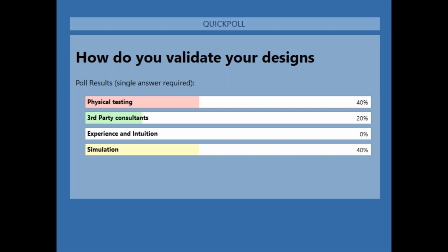So what we do, I'm not saying no physical testing at all, because we test our systems all the time. But these tests are generic, and then maybe run a simulation and compare at least your deflection, your displacement in the simulation software to what you've actually got on the probes during the physical test. That's how, through experience and being involved in testing, I validate my own simulations.